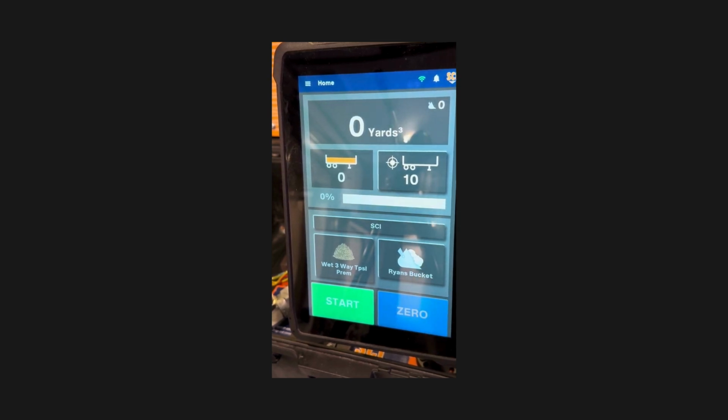We have a prox sensor that mounts at the pivot pin of the bucket arms. It's got 2 prox sensors on it. They span about 3 inches between the 2 of them. We use the edge of the bucket arm as the target. We're running ferrous prox sensors, so we have no need to weld or mount targets onto the boom. We're using the boom as the target.